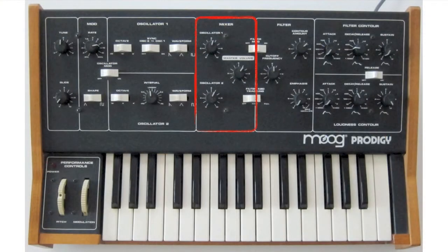For the final demonstration, we'll look at the sole modulation configuration for the voltage-controlled amplifier. Similar to the VCF, we also have an ADSR hardwired as a modulation source to the VCA. This envelope generator has the same features and limitations as the one for the filter. Let's watch the demo.